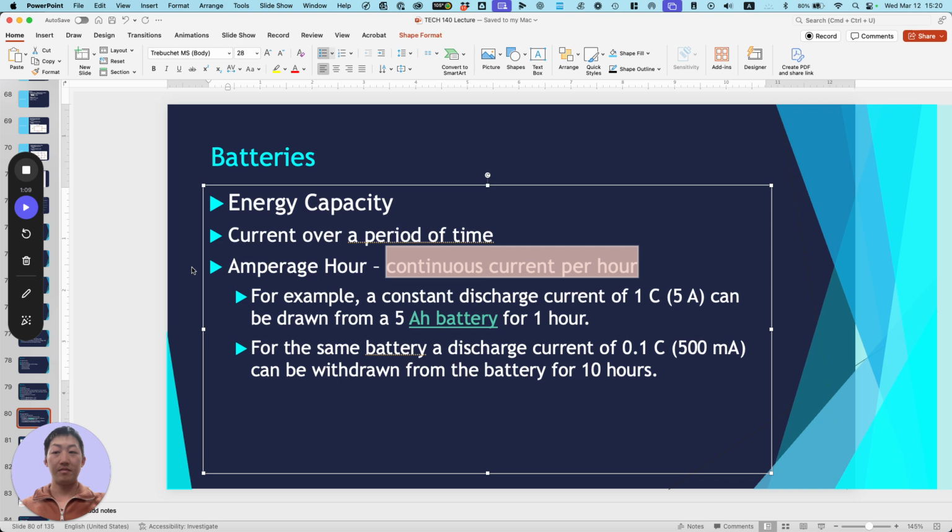All right. The other thing I was gonna show. Oh yeah. You saw that they mentioned that some batteries have a circuit on top to help control overcharging, right? Because overcharging would also potentially cause a thermal runaway. This one does not have that. That's the DJI. And that's why it's important that you set the right settings here, because we don't want any fires here.